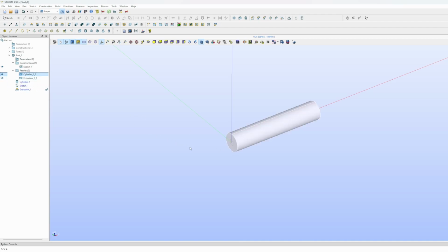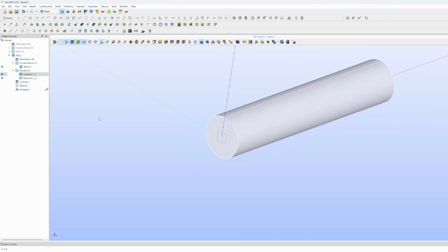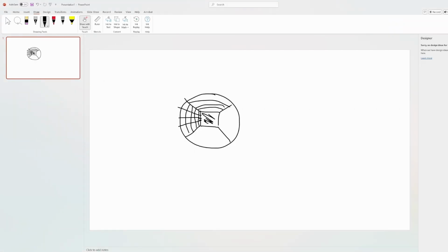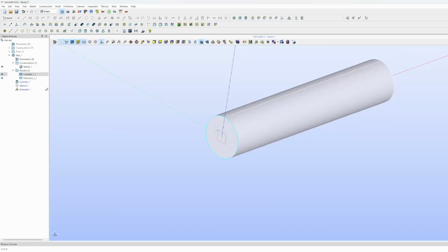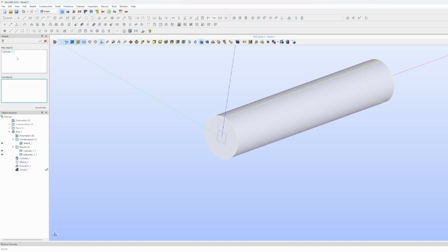But these are separate objects, and I want to create this guy. To create this, we need to create subregions, having 4 sides, each of them having 4 sides. Okay, to do this, I will create a combined region between this cylinder and extrusion, and I will use this smash. Okay, click the smash, and the main objects should be cylinder.